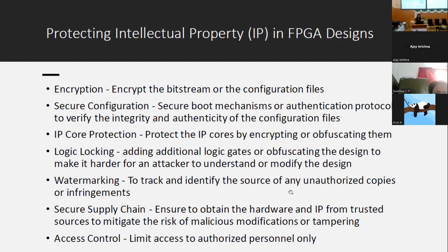So how will we protect it? First of all, through encryption. Encryption of what? Here we are dealing with hardware, not software. In software, encryption means encryption of data. In hardware, it is encryption of the bit stream. I told you, right? The FPGA gives output as a binary file. That binary file represents the hardware logic. So encrypting that bit stream is one method.